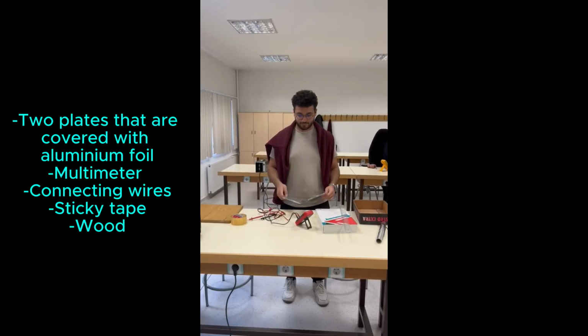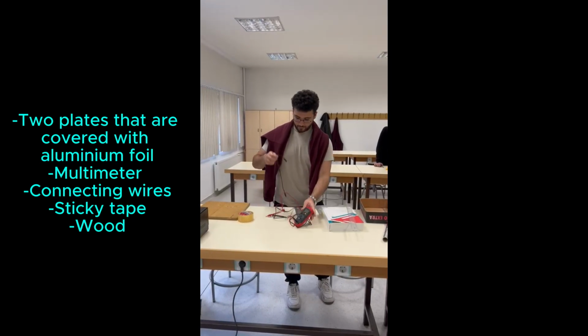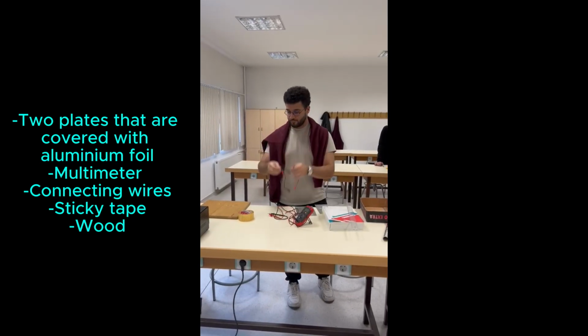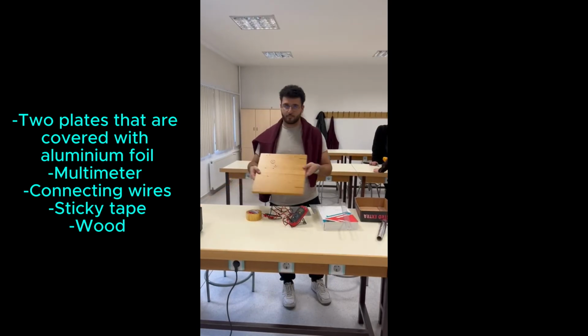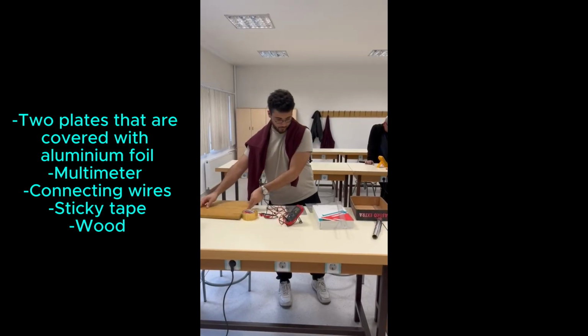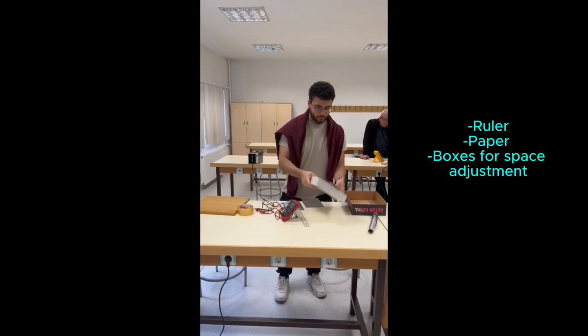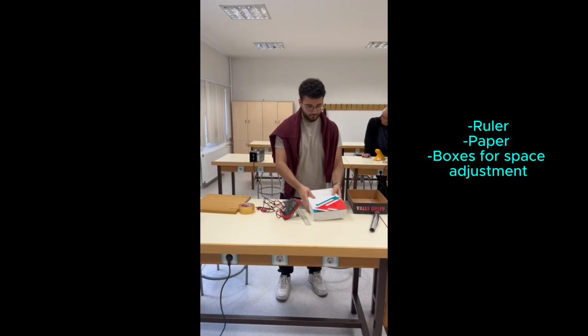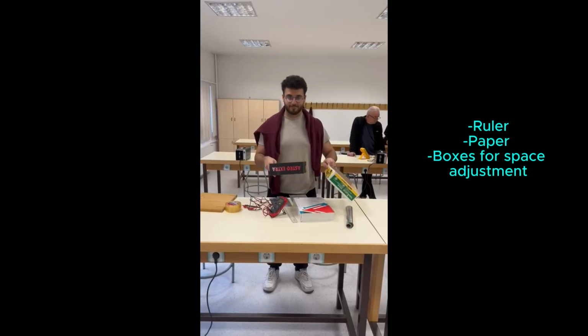Therefore, for these experiments, there are some required equipment: two plates that are covered with aluminum foil, a multimeter to measure the capacitance, connecting wires, sticky tape, wood as a dielectric material, a ruler to measure the distance, paper for the dielectric material, and boxes for space adjustments.